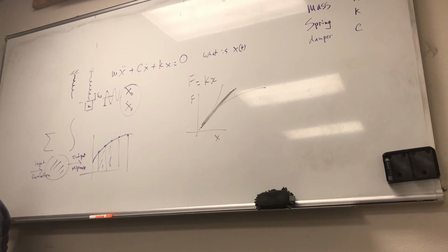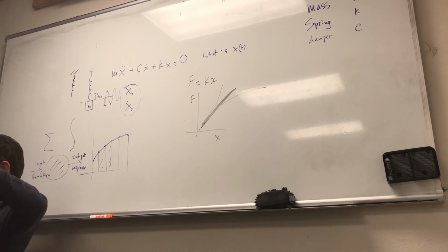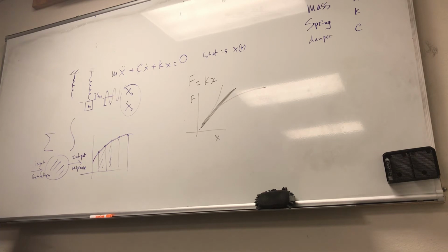So the equations of motion can be derived conveniently by drawing a free body diagram of all masses involved. For a vibrating system, if it's 1 degree of freedom, that implies you have one mass that you are dealing with. If it's 2, it's 2. So when you do a free body diagram, you do it on the mass. Forget about the spring. For the spring, you just figure out, is the spring elongated? That means it's pulling on the mass this way, etc.